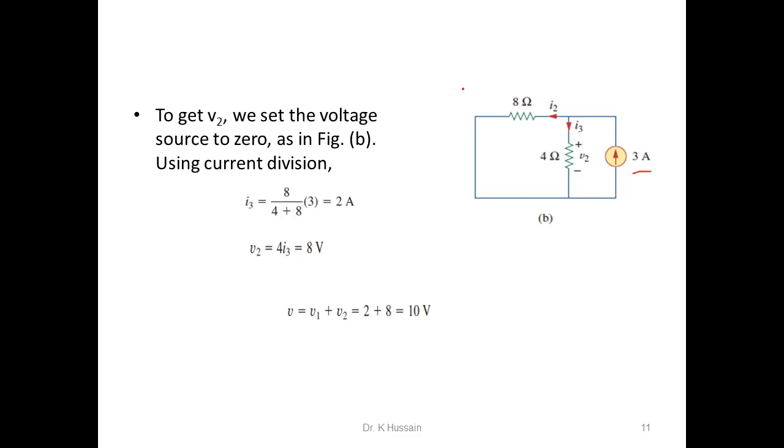So at that time, here actually it was a voltage source. But when a single source is acting, this voltage source should be short circuit, right? In the previous case, the current source was an open circuit, but this one is a short circuit. Okay, you need to understand why you are keeping a short circuit and why you are keeping an open circuit, where you have to keep this one. Okay, then now only one source is there, the current source.